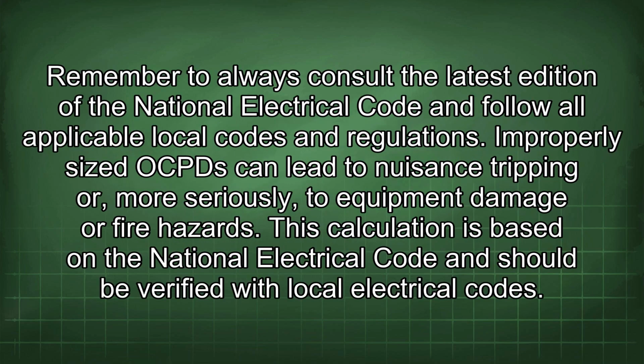Remember to always consult the latest edition of the National Electrical Code and follow all applicable local codes and regulations. Improperly sized OCPDs can lead to nuisance tripping or, more seriously, to equipment damage or fire hazards. This calculation is based on the National Electrical Code and should be verified with local electrical codes.